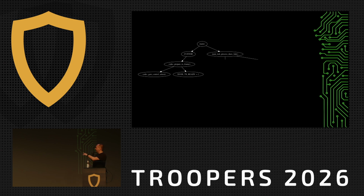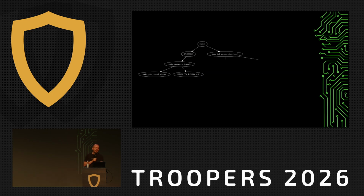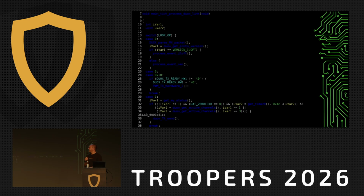And on the right, that's the other function that we just saw, the main tick process DUOX link. That's called there, right? So let's take a look at it. This is the function, main tick process DUOX link, and it forms a data packet when a time division slot is available. On line 36, you can see that it calls the DUOX send function.